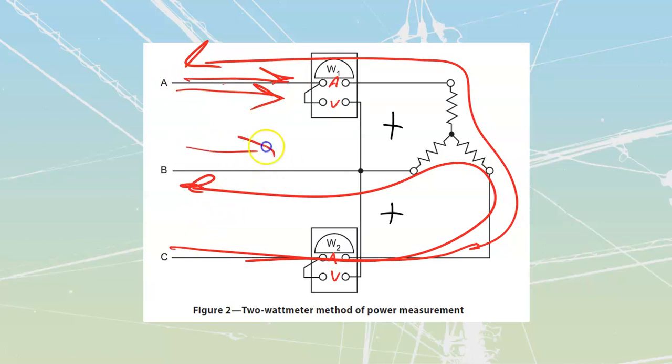And then our B is going to have both currents going through and splitting, etc. And so it cycles through all 3 of those phases, and we are able to actually pick up and read the entire value, because there's always going to be one that any given instant is going to be higher. Now this is happening at a frequency of 60 hertz, so too fast for your human eye. It's basically going to push the needle over far enough that you are going to hold at whatever that maximum is, but that maximum that it's reading is going to be all of this over here.